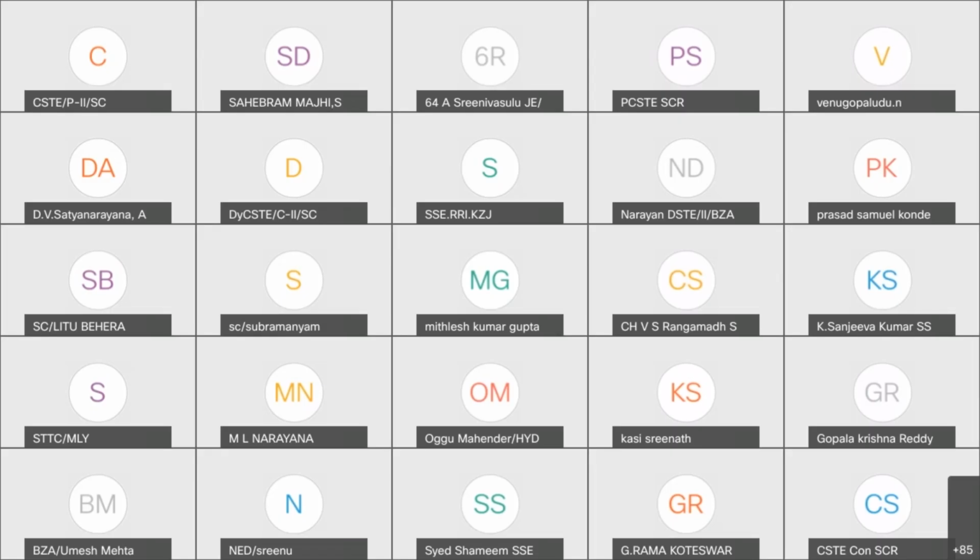Sathyanarayana, in RRIs where a number of points are to be operated for a route, definitely there is staggering of initiation of the point operation. Even other than RRI, even if one crossover has to be operated, the triggering of initiation of point operation is not simultaneous for both points. I think after one end, only then the other end point will get the operation initiated. So actually, this staggering will be in milliseconds only, sir.